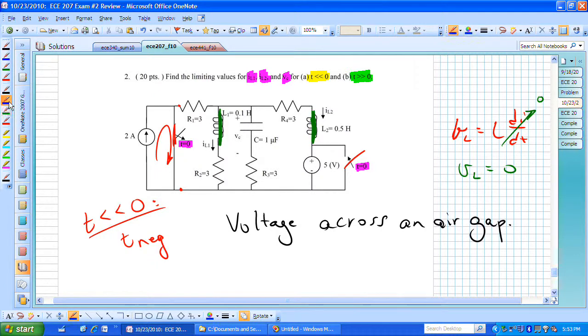If we look at ICE, which says that I is equal to C dV dt, again, after voltages and currents have reached steady state, this voltage is going to be constant. Its time rate of change is 0, and consequently we have 0 current flowing through that capacitor, and effectively we can get rid of that. That particular capacitor is removed or opened up as a circuit element in its steady state condition.